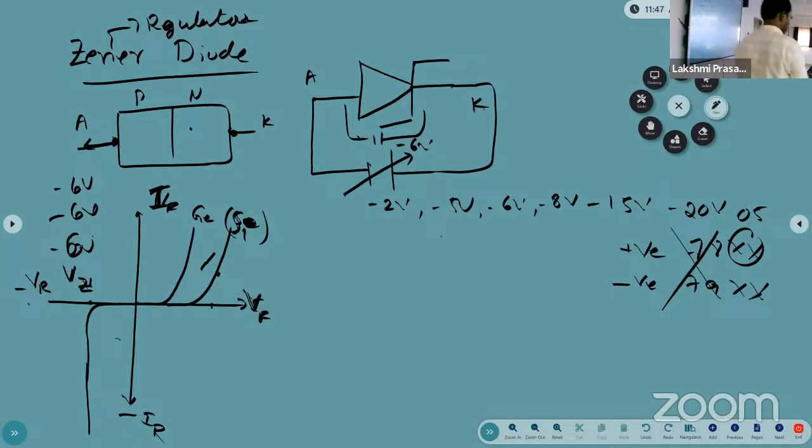In the exam, if the question is like explain the Zener diode working operation, then you can explain the forward bias. How you prepared for the PN junction forward bias, the same content you can write here. For the reverse bias, you change the content only. So we are improving the impurity levels, so that after a certain voltage, it gives a constant voltage across the diode. Due to that, the diode is acting as a voltage regulator.